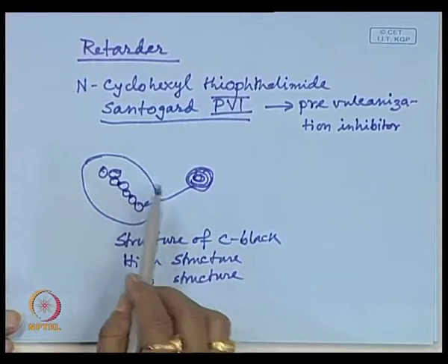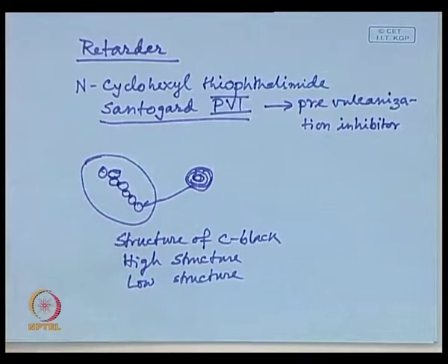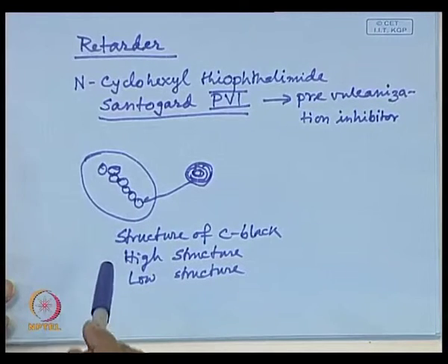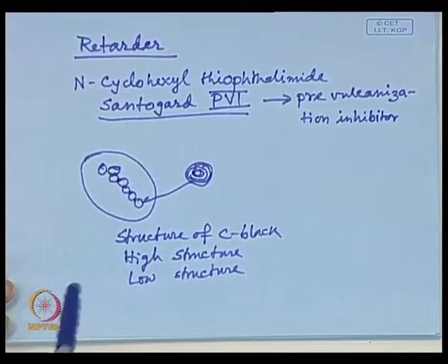Now, again they dictate the processing characteristics of a rubber compound while carbon black is used as a filler, for incorporation and dispersion. It has been found, it has been experimentally verified, that high structure carbon black is difficult to incorporate in rubber compound, but it is easy to disperse. Please note it down.